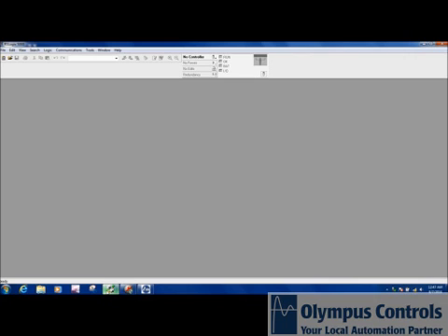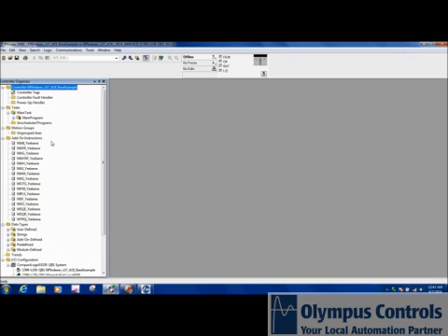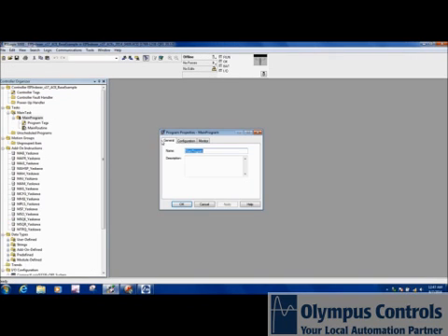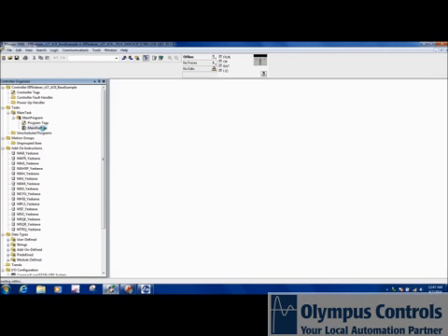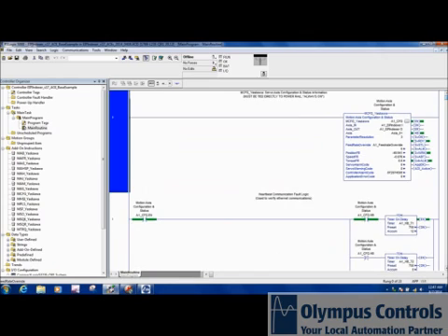And then once you do that, you can open up the sample RSLogix 5000 program that comes with the Yaskawa Ethernet IP drive. I'm going to open that up in offline mode. You'll see this is the same program that we were looking at before. It lets you do everything that is possible with the drive: jogging, moving, indexing, sequencing.